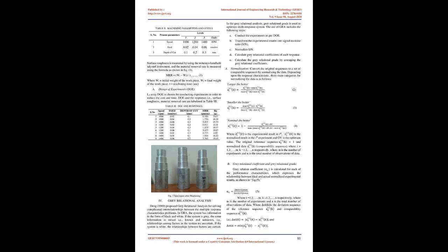It is clear that speed, feed, and depth of cut have significance on machining various alloys with various reinforcements. It is evident that no literature is available on turning of AA2024/SiC metal matrix composites, and this motivates us to investigate the effect of process parameters on surface roughness and material removal rate. AA6082 was chosen because it possesses good formability, weldability, machinability, and corrosion resistance, with good strength compared to other grades of aluminium alloys. 2. Materials and methods.